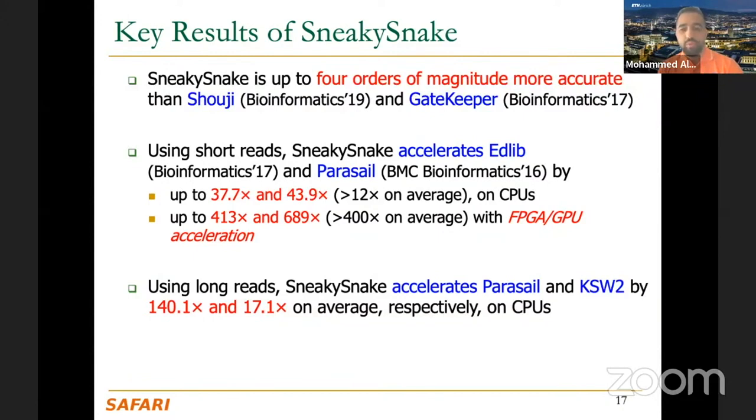And they also have 2 configurations, with path and without path, that is to say with generating the CIGAR and without generating the CIGAR. But EDlib is calculating only edit distance at the end, or Levenshtein distance. For Parasail, it does the full sequence alignment. And these are the speedup numbers, as I said, where we implemented on FPGAs, GPUs, and CPUs.